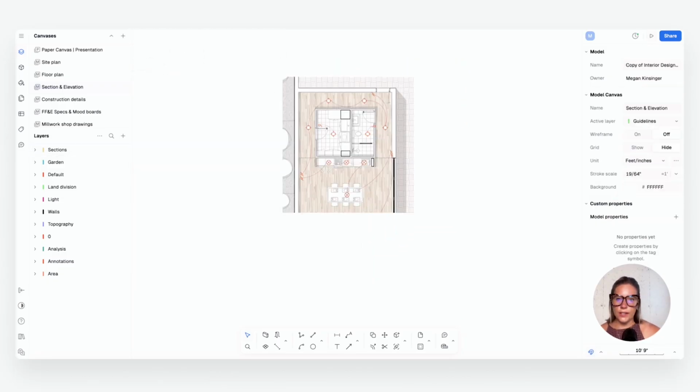When you are choosing your section cut, you just want to make sure that you choose something that is going to convey multiple rooms, cut through multiple doors, multiple windows. And this is really going to help explain the relationship between different spaces. Now, for instance, this one that we're focusing on is more of an intimate space just for teaching purposes, just to not overwhelm you. But you should be able to take what I'm teaching here and apply that to any other section cuts that you do. So this section cut is a little bit more simple just for the demonstration.